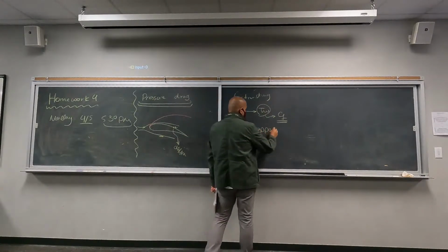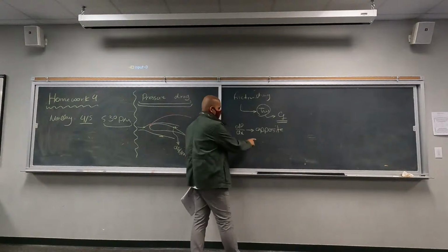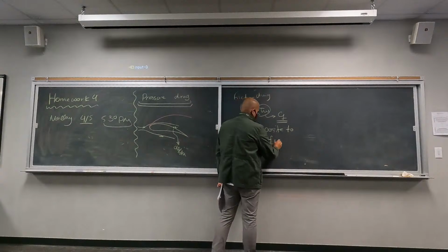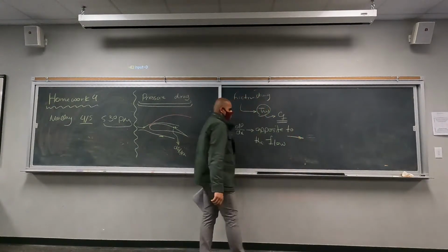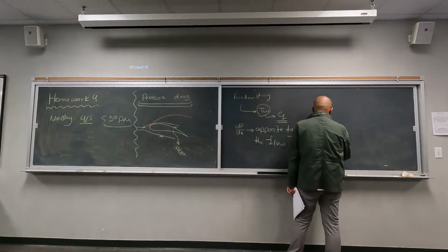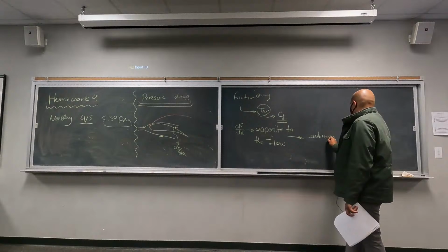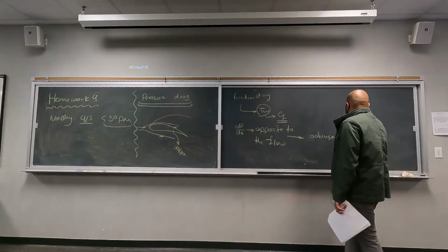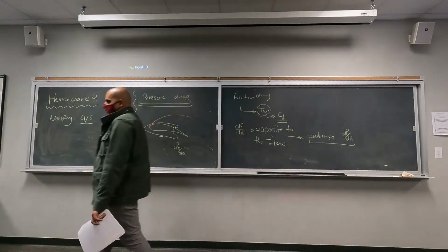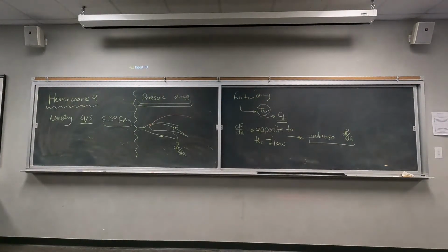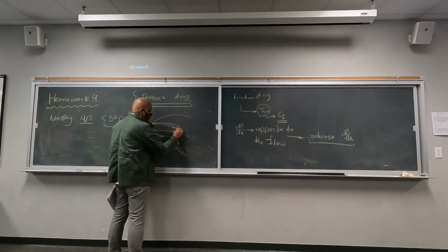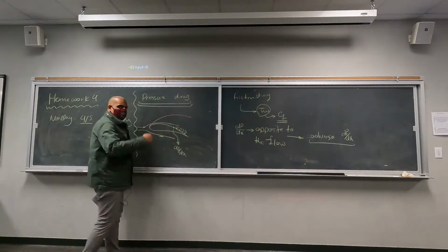Opposite to the flow. And this is the thing we call adverse pressure gradient, adverse dp/dx. Because of this adverse pressure gradient, we are going to see the formation of vortices, or flow moving in the wrong direction.